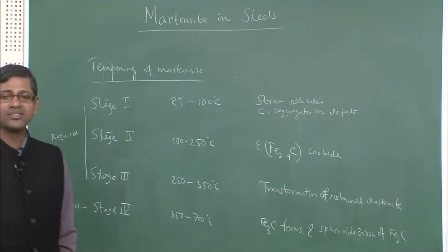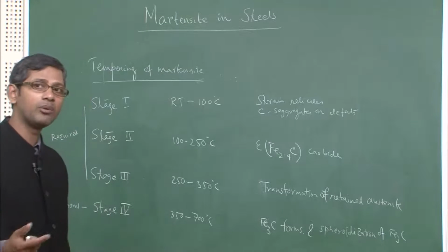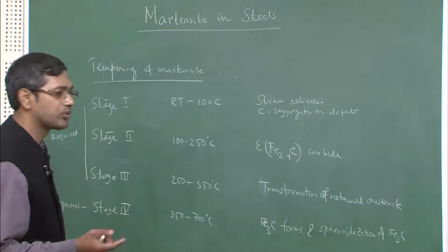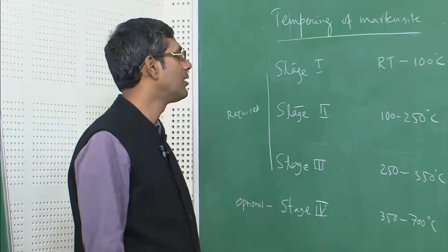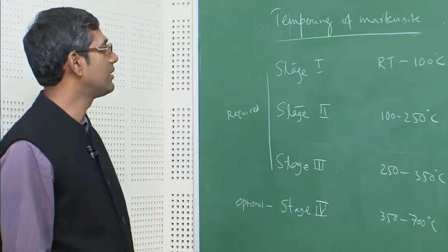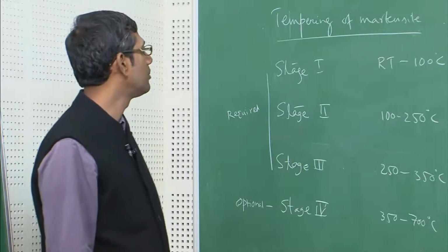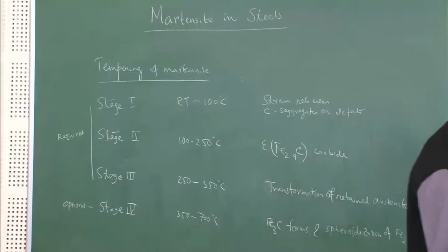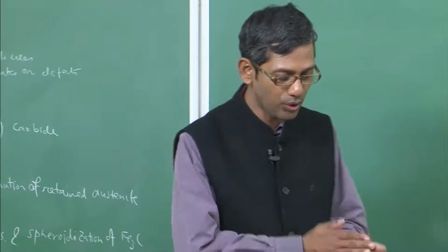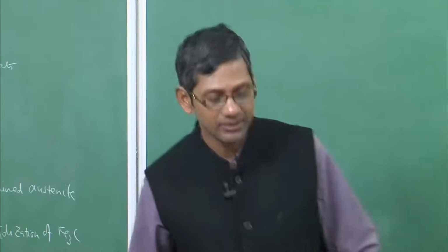Well, in case of alloy steels, you can form other carbides. If you have moly present, or suppose chromium present, then you can form those carbides also in addition to the epsilon carbides. So, that is basically the aspect of the tempering of martensites, which is routinely done. Now I am going to go back to the slides, and in whatever time I have, about 10 minutes or so, I am going to start the discussion on the last topic on austenitic transformation, that is austenite to bainite transformation.